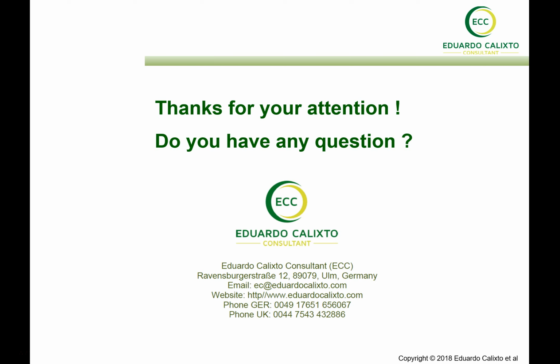But we see that first we need to link the RCM activities not only to the maintenance system, such as CMMS or SAP, but also to the asset management system, and we need a platform that integrates all this information, concerning not only the maintenance plan but also corrective action, safety issues, and so on, in order to prioritize which actions will bring the best cost benefits in terms of performance achievement for a process plant.